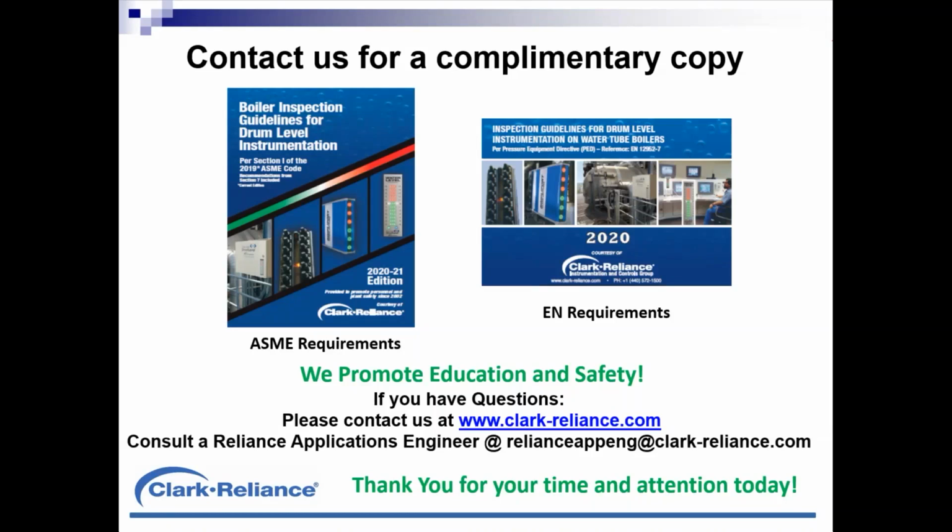First of all, the code requires that a level instrument cover the full operating range. So that's going to go from the low water cutout up to at least what would be high alarm. So the boiler manufacturer is going to make that determination. They're going to determine that range, how that device should be attached on the piping, and that would be your starting point. I'm not sure what he's getting at by shrinkage and changes in level. If he's talking about density error, that we can address in a more detailed conversation if they wish, and I would encourage them to contact me directly.